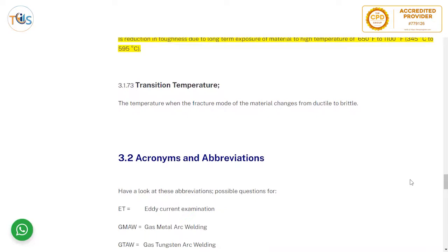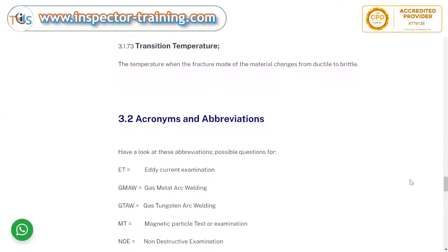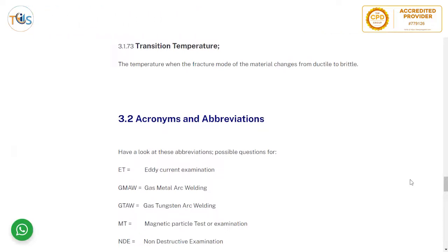Even at ambient temperature for a hydro test, the equipment or the pressure vessel fails many times. Because it was high load and there was ambient temperature, even that can be a transition temperature for thick low alloy steel or carbon steel material.